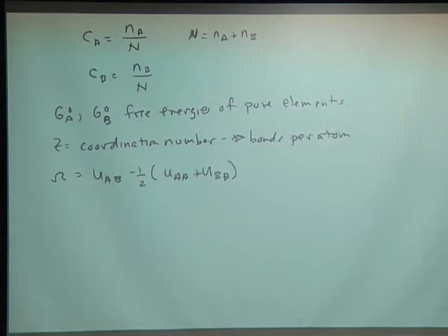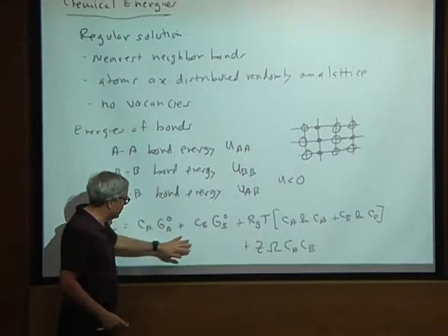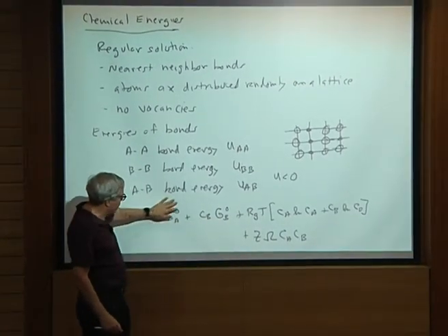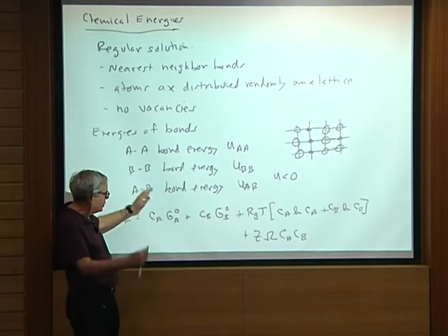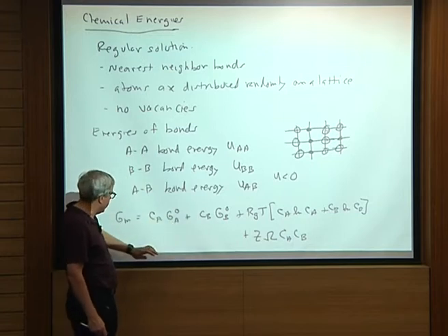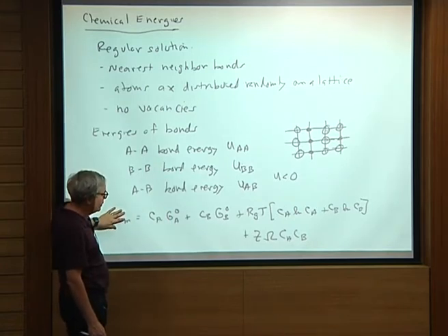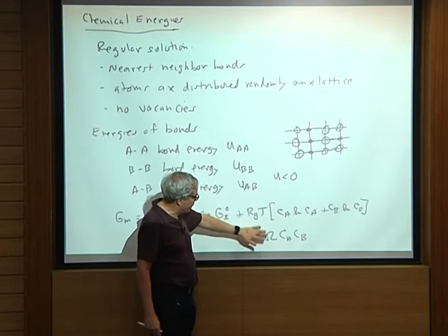Okay, so if you look at this omega parameter here, so let's go back. You have a couple of terms here that I want to highlight for you. So these are the standard state terms. In fact, probably not all that interesting. These are terms that basically just set the intercepts of the free energies with the axes CA equal to 1 and CB equal to 1. In fact, sometimes you'll see this written as this term pulled over here as a delta G, or the mixing energy.